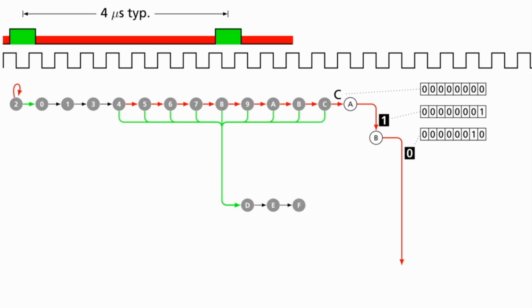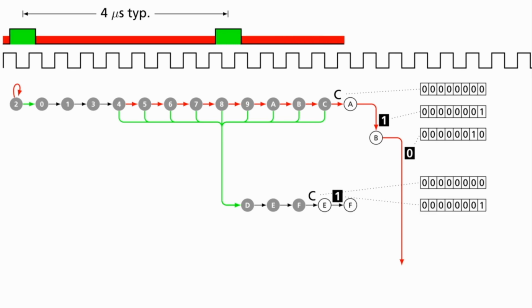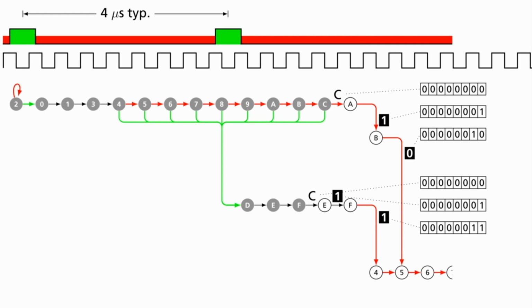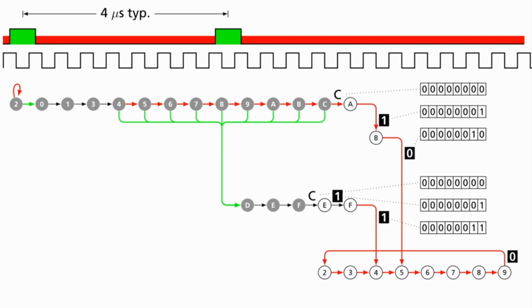Then it waits a couple of cycles, and again clears the register, shifts the leading 1 as before, but this time it shifts a second 1 since we saw a second pulse. At this point, the sequencer has seen 2 bits at the start of a byte, so it starts looking for the third. As before, it must wait a few more cycles before it can declare there wasn't a pulse, and therefore it saw a 0. But if there is still no pulse, it shifts a 0 into the register and starts looking for the next pulse. And the process repeats every 8 cycles.